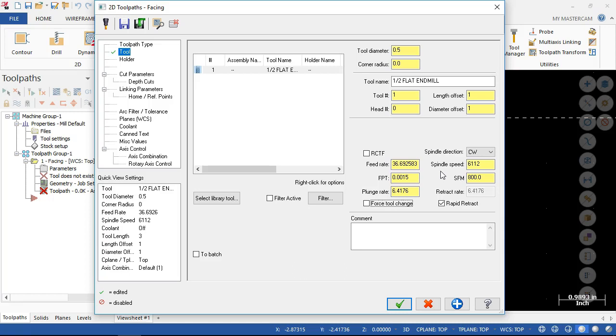All right, that's all still going to be based on the tool material and the diameter. So if I look at the manufacturer recommendations and it says that I can run at 1,000 surface feet per minute, then I type in the 1,000 and get 7640. If I have a 7,500 RPM spindle, I can run it up to 7,500. All right, so my preference.